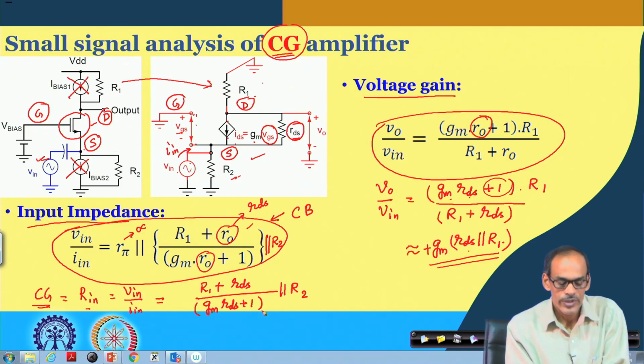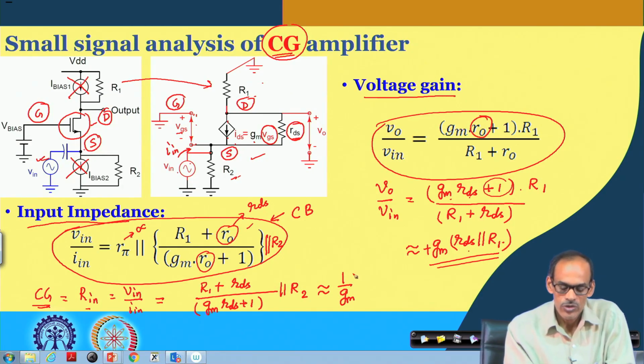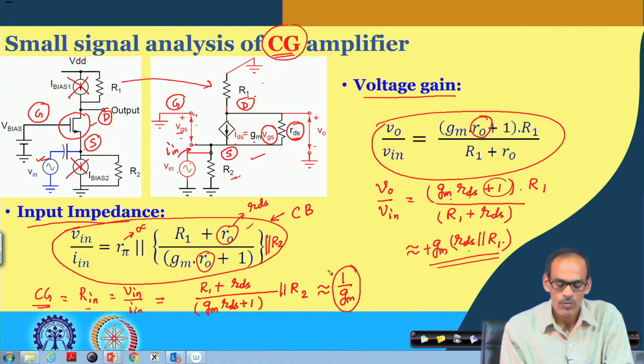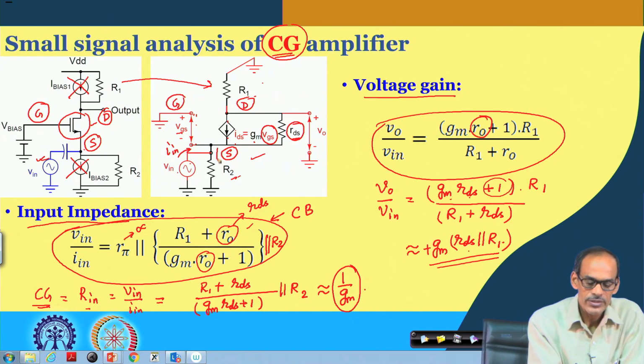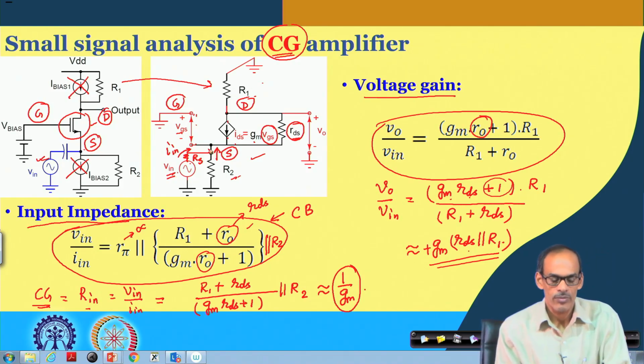Again, here we can approximate this input resistance by 1/Gm, and even though this 1/Gm of MOS transistor and BJT have a different order of magnitude, still 1/Gm is quite low. So, since the input resistance is low, the same problem will arise if I consider source resistance, signal source resistance Rs, and this voltage signal will have difficulty reaching the common source.